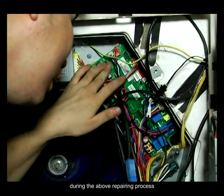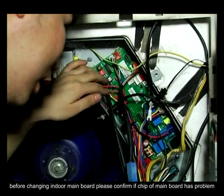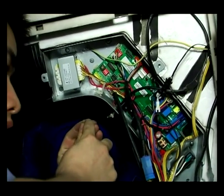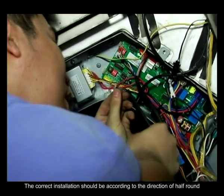During the above repairing process, before changing indoor main board, please confirm if chip of main board has problem, or the pins of chip have fallen off, or the chip is installed in the opposite direction. The correct installation should be according to the direction of half round.